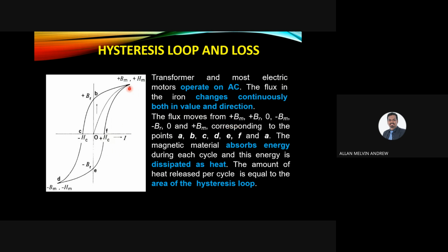plus Bm. So from here, it is only considering the hysteresis. So we have seen it move from here to here. Plus Bm moves to plus Br, then it moves to 0, then it moves to negative Bm, then it goes up to negative Br, then moves to 0, then moves back to plus Bm. As mentioned here in the sequence, we can also relate it with A, B, C, D, E, F,